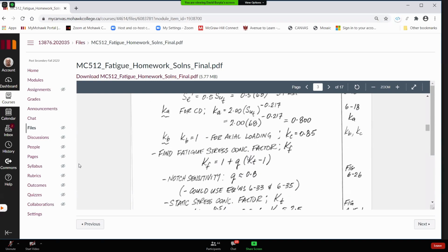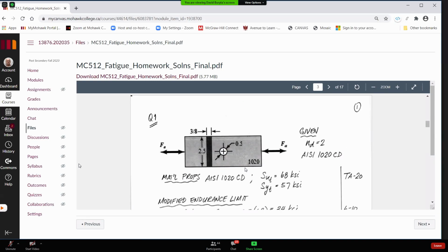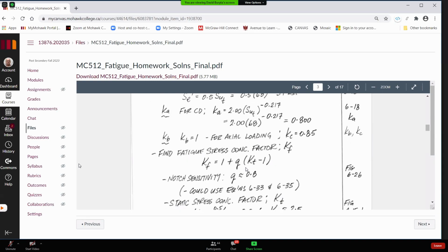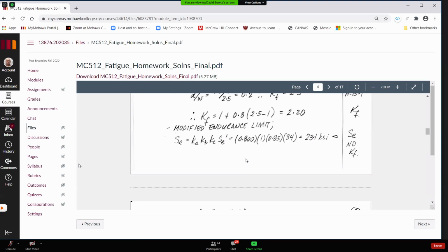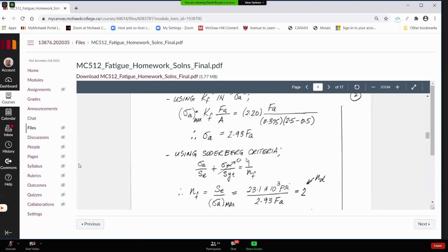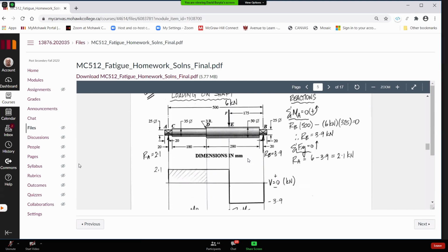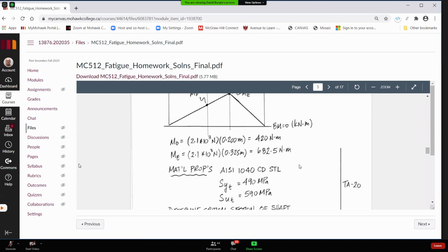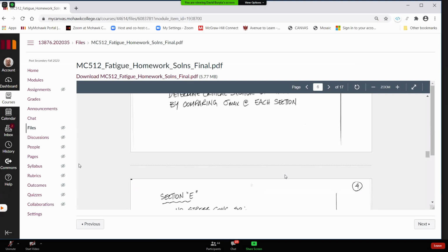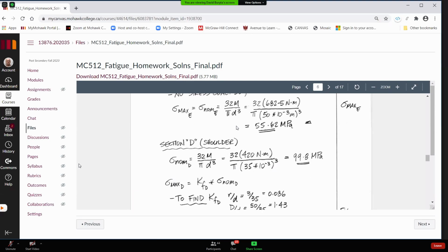So you'll see this one here, it just gets into the idea of finding the KAs and KBs. And because it's non-rotating, you have to use the DE, right? And then here you can see we have the shaft. We draw the shear and bending moment diagram after you find your reactions, right? You look up your material properties, and then you start to look at your...